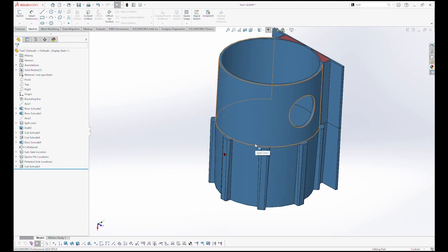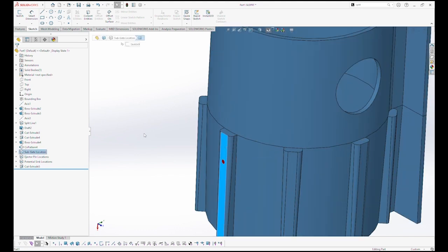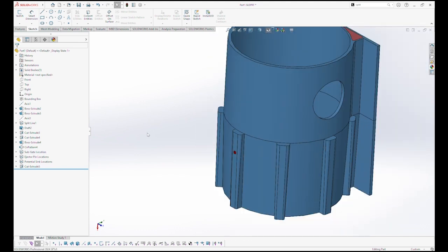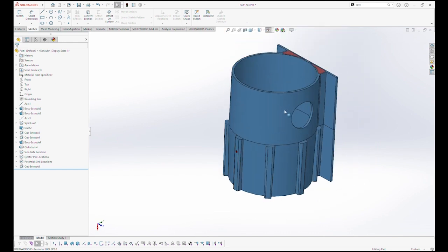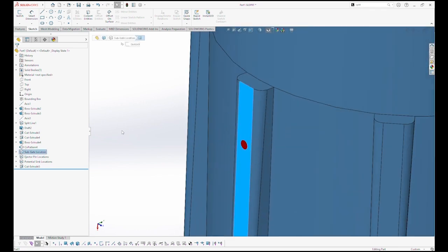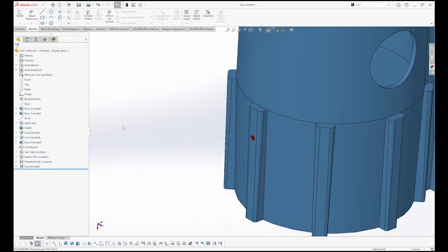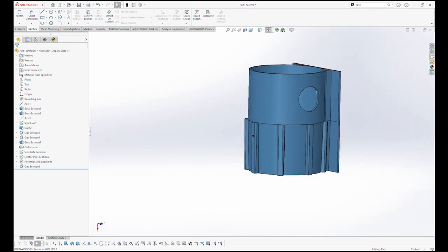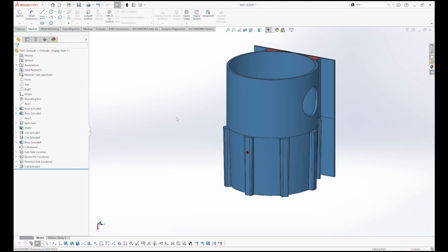And so sometimes you might want to consider putting in a flat on a round part, even though that flat doesn't perform any kind of function in the end form, fit, and function of your design. It certainly provides a function for the manufacturability of the part, and that flat oftentimes doesn't cause your end form, fit, and function to suffer in any way. But just understanding the need for a flat for a gate can make all the difference as far as the manufacturability of a part and the cleanliness of that gate vestige during the molding process.